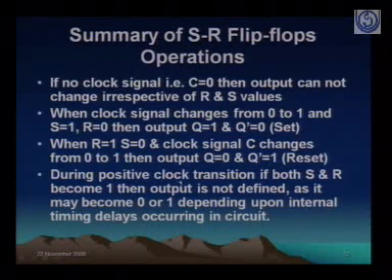And during positive clock transition, if both S and R become 1, then the output is not defined, as it may become 0 or 1 depending upon the internal timing delays occurring in the circuit, and that's why we don't want this condition to occur within a flip-flop system.